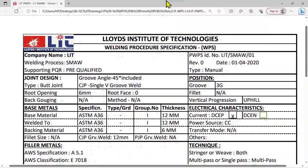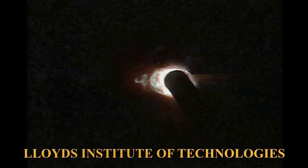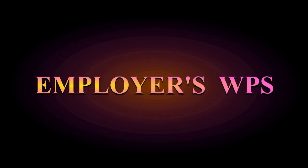Out of these welding processes, let us start with SMAW, which is the most widely used welding process all over the world. To start with, let us take step number 1 of my last video, that is, identify the welding process to be qualified and the code you are going to follow. That means the management has to take a decision that we will go according to a particular code.